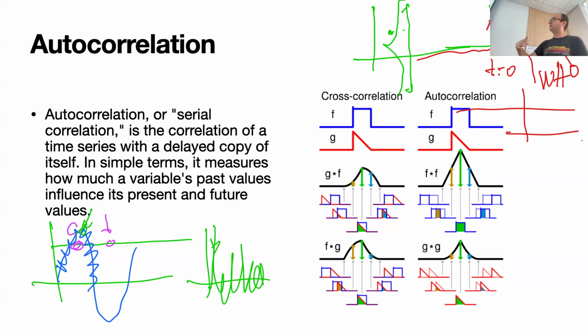There is an additional thing called cross-correlation, which we are going to use also, but it's the same concept. It doesn't say something about my signal alone, but says: if I know that F is here, do I know where G will be? Can I predict the other one? It's not a situation that goes both ways. There is a cross-correlation from F to G, and a different cross-correlation from G to F. It doesn't mean they're the same, because one signal might be more informative than the other.